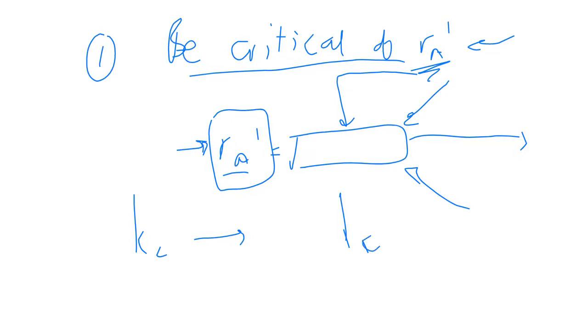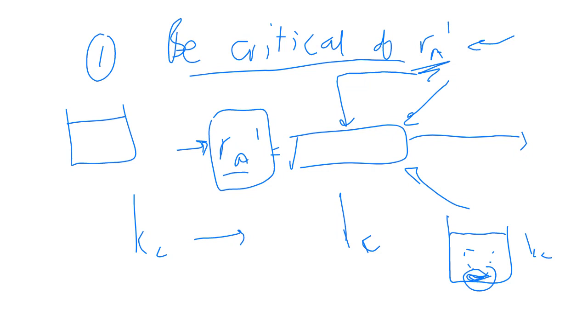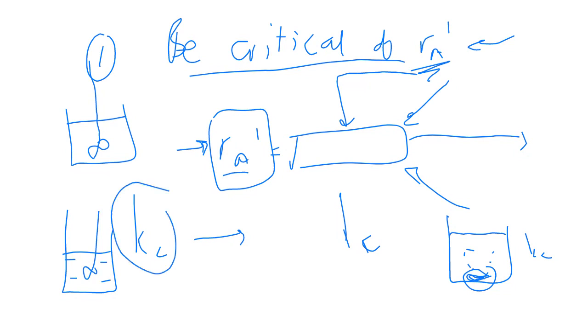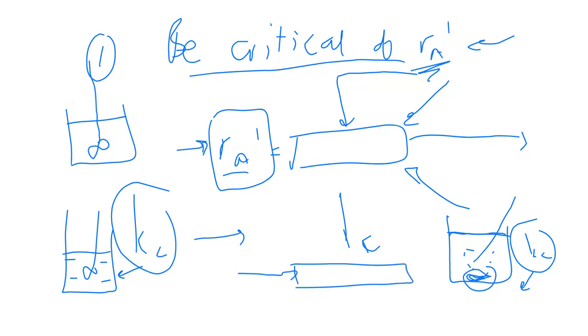You cannot. Even if I have a batch reactor, this guy might be using a magnetic stirrer at the bottom, and that is going to have a different Kc profile to when a reactor is used where I have an overhead stirrer. Or if I have a CSTR and some baffles, Kc is a reactor-specific parameter. I cannot say, oh, this guy in his reactor had a Kc of that, so therefore I'm going to use a similar Kc, at exactly the same temperature and inlet conditions, in my packed bed reactor when I design it.